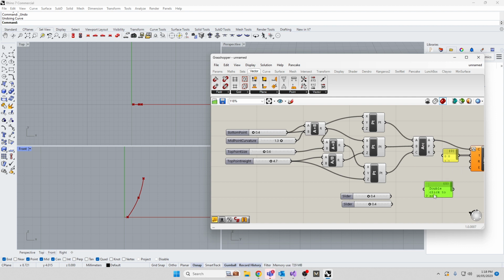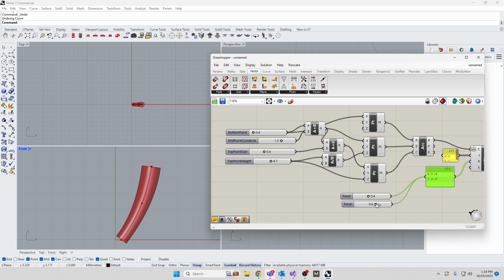And we're going to add multiple inputs to this. So we're going to drag the first one, and then using Shift, we're going to drag the second one. All right, and you can see that as I now change this, I can change the numbers that are in this panel. So at 0, I want 0.4 mil, and at 1, I want 0.6 mil. So when I connect this one into here now, you can see in the screen I have 0.6 at the end, and I can make it bigger, smaller, thinner, fatter, as I need.